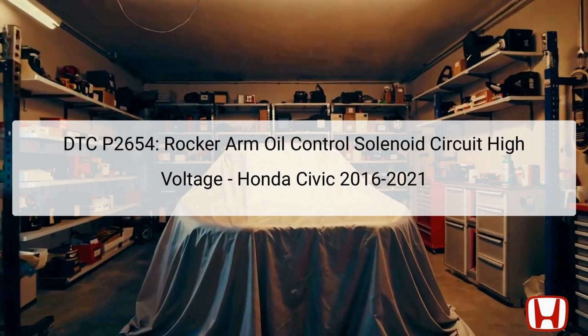The DTC P2654 refers to a problem within the rocker arm oil control solenoid circuit, indicating that the circuit is experiencing high voltage levels. The rocker arm oil control solenoid plays a crucial role in managing oil flow to the rocker arms, which directly affects engine performance and efficiency.